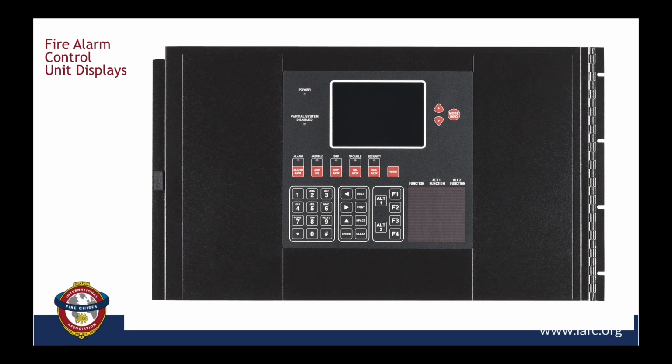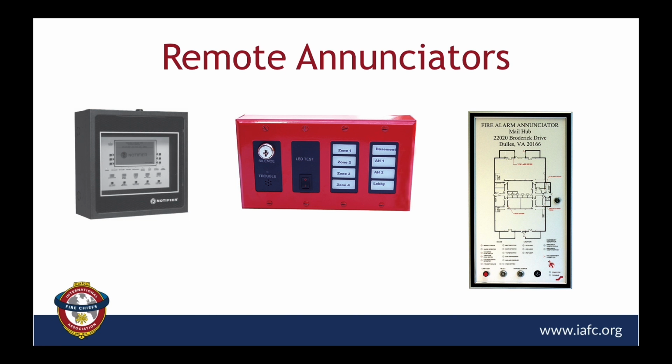If it's a supervisory condition, you've probably got something that needs to be looked at because the system is potentially not going to function properly. And then if it's a trouble condition, well, there's a lot of reasons for that, but if you look at it and the panel's not smoking and the panel has primary power, that is going to need a repair organization to come out and diagnose what that problem is. But that's where that's at. Next panel, please.